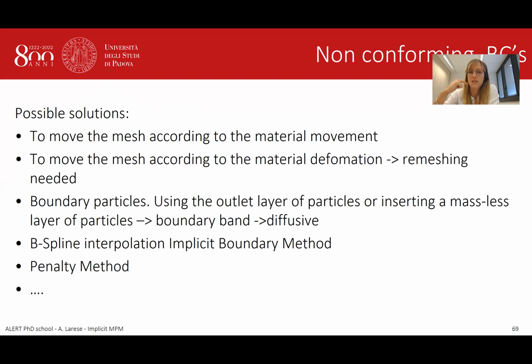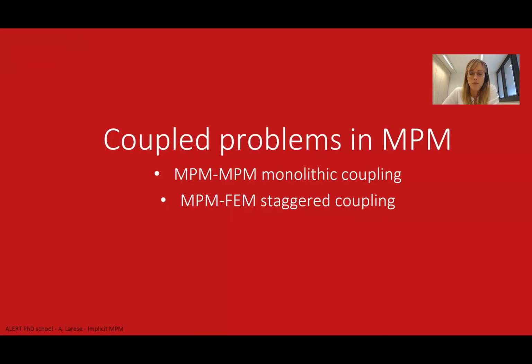I don't think it's still available for large deformation, if I remember. I mean, it's proposed for small deformation. Alternatives are the classical alternatives of finite elements: penalty methods and Lagrange multipliers. The main drawback of Lagrange multipliers is that you're adding degrees of freedom and you don't want to change the structure of your matrix. Penalty method is indeed the simplest method, very precise, very effective. It has the problem that it can ill-condition the matrix you're solving.